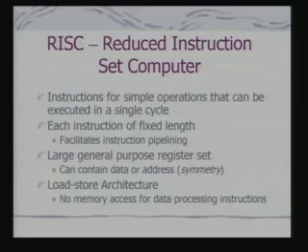On the other hand, we have RISC, or the reduced instruction set computer. As the name suggests, here the basic objective is to have a smaller number of instructions, and instructions are designed in such a way that they perform single operations that can be executed in a single cycle. Also, instructions are of fixed length. A fixed length instruction facilitates what we call instruction pipelining, because I know that if I am fetching an instruction